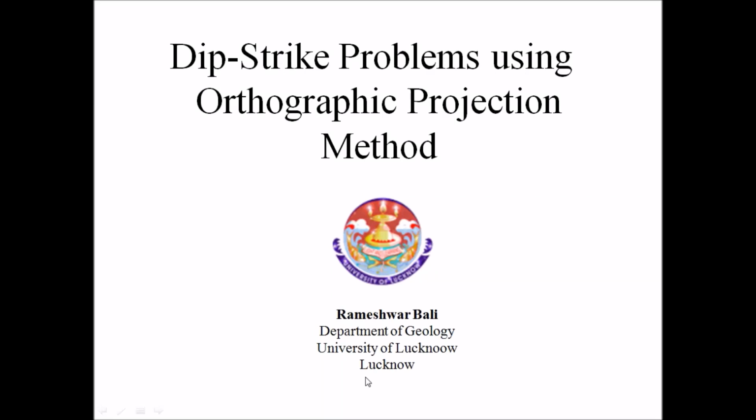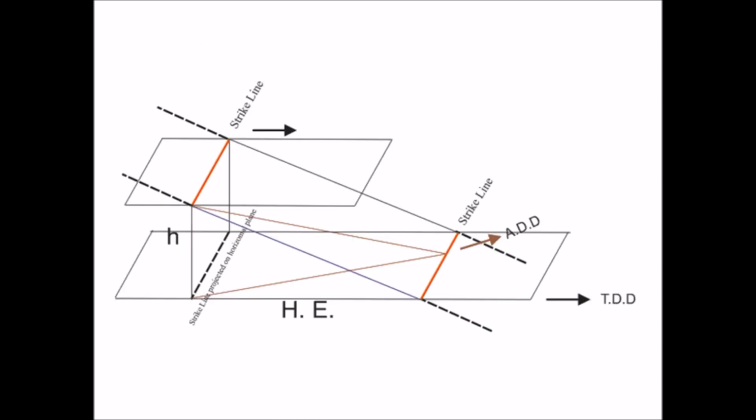Good morning, everybody. Today we are going to learn dip strike problems using the orthographic projection method. You are all aware of the basics of dip and strike. Here I will just try to revise.